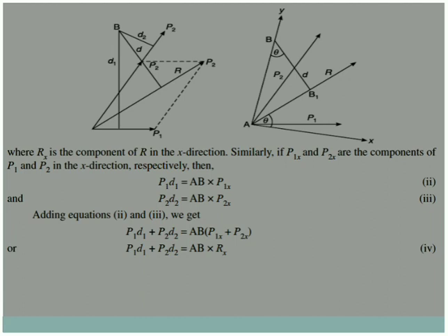P1 into D1 is equal to AB into P1x, where P1x is the x component of force P1, and P2x is the x component of force P2. Therefore we get equations 2 and 3. Adding equations 2 and 3, we get P1 D1 plus P2 D2 is equal to AB, which is common in both, into P1x plus P2x.